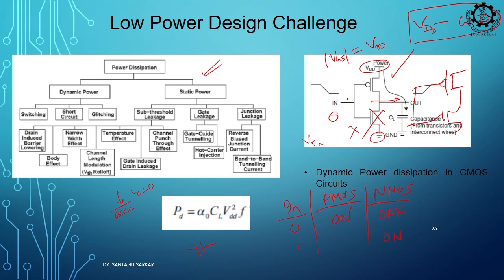You think of mod of VGS, it will be easier rather than considering VSG. If V in is greater than VTH, then only it will turn on, right. If input is greater than the threshold voltage, then only it will turn on. So, when input is 1, my PMOS goes off. See, they are complementary. If one turns on, another is turning off.